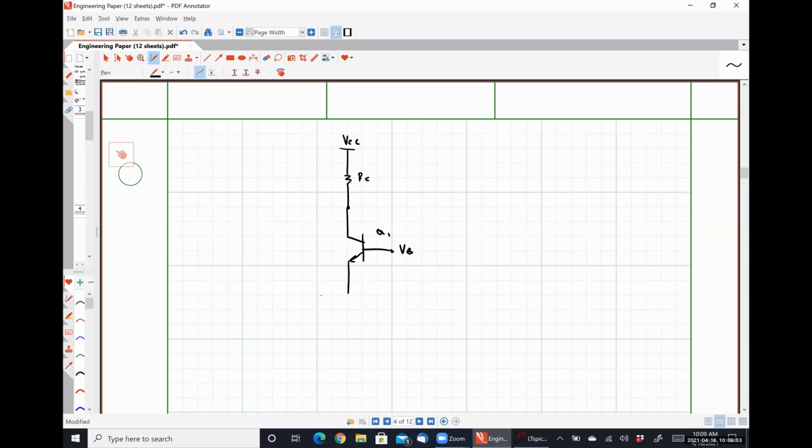Transistor Q1. Now our early effect resistance, R out, is going to be our feedback resistor. If you recall, this is something the textbook said was too hard to deal with, which is why for all the common base amplifiers, you never see anything in the textbook with regards to what happens when the early effect is included.